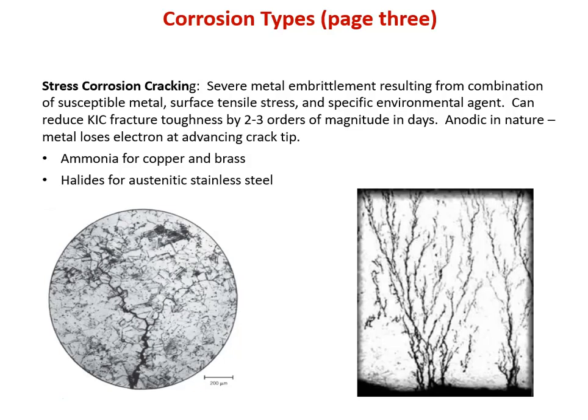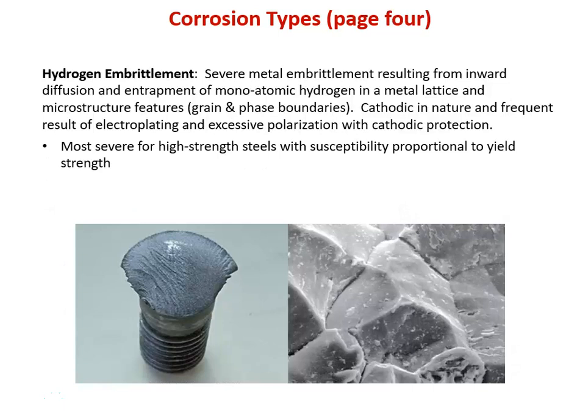There's even a special name for the K1C in these aggressive environments, and that's K1SCC, meaning fracture toughness in the mode 1 crack opening direction under stress corrosion cracking conditions, K1SCC. You'll actually see that in the literature. So these are very important to remember, and they're luckily well documented. It goes under material selection.